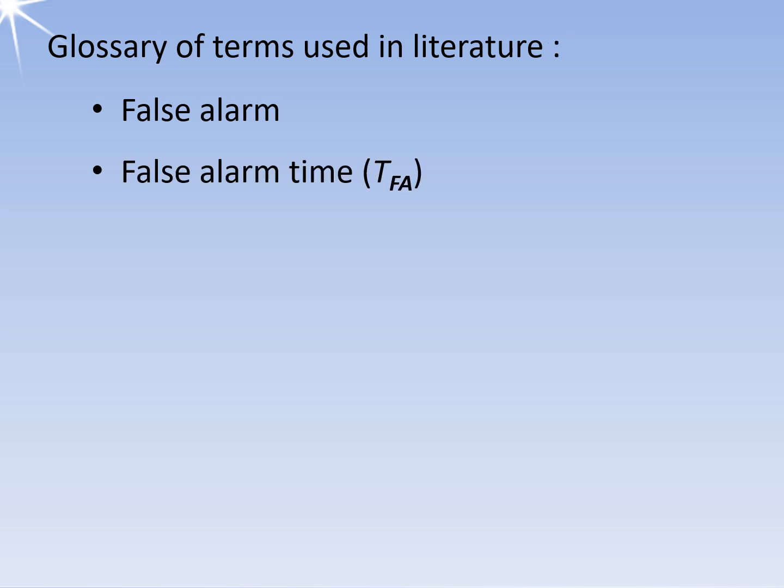The average time interval between the false alarms is called the false alarm time. The false alarm rate can be calculated for a given false alarm time. The false alarm rate is the ratio of the number of false alarms to a constant reference value, which is usually related to a radar's pulse period. It's important for a radar to keep the false alarm rate as low as possible. A high false alarm rate increases the risk that an alarm will no longer be considered highly relevant.